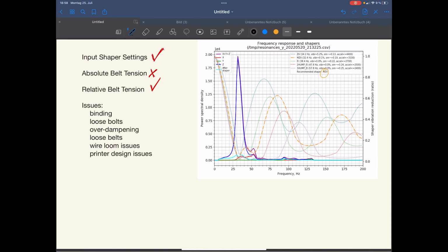But if we are looking at, for example, we are running our print farm, and we are mostly printing big parts with less details, like parts for printers, for example. This part will be looking fine even at much higher accelerations, because the frequency of the movement changes here is much slower than the peaks where we are going to, and so those peaks are not actually part of our movement, and therefore it doesn't really change something.